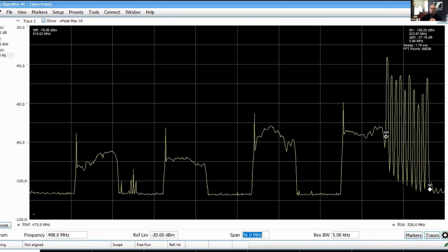So now that we're working with that equidistant grid and we're not worrying about intermodulation anymore, we can put a lot more channels. So a lot of people have said to me, well, 92 channels, I don't need 92 channels. How is that helpful to me? Well, when you go to the real world, it's always going to be reduced. You're never going to find a situation, again, unless you're in an isolated space, where you'll be able to use the entire spectrum. So a lot of times half or maybe 75% of your spectrum is filled. So if you're able to do equidistant grid and you have 56 megahertz to work with Evolution Wireless Digital, if 75% of your space is filled, you could still get like 24 channels, 23 channels in that space.